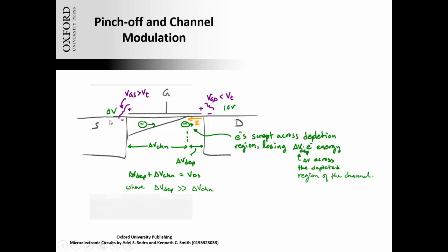So here we have on the left the source well and the drain well on the right, and I'm depicting here this channel, the induced channel, which has an initial depth on the left due to VOV, VGS minus the threshold voltage. And now I've exaggerated what actually happens on the right side. You see that I'm showing that the channel pinches off at a location X. If we say X is 0 here at the source and X is equal to L at the drain, it pinches off, it goes to 0 depth at a location X that is less than L. Now, like I said, this is exaggerated. I've made this probably a lot longer than it actually is.